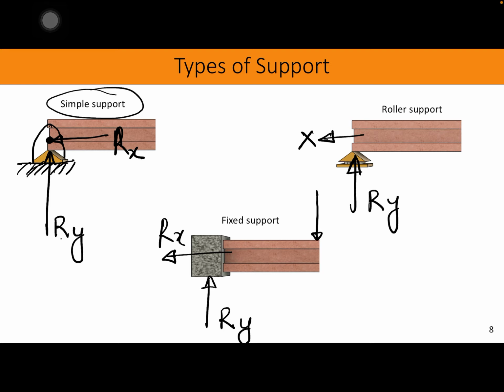How? If we apply a load right here, then there is a resisting moment right here as well, so this moment, right? However, if we apply a load in pin support, this is free to rotate or free to move, right, up and down, so there is no resisting moment. In that case, roller support, we don't have any moment. Same goes to here. See, if we apply a load right here, it is also free to rotate, it doesn't have the moment.